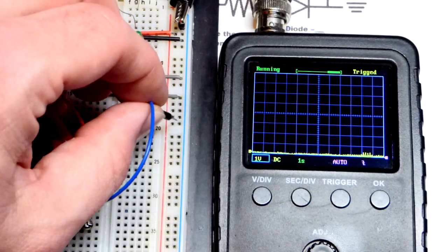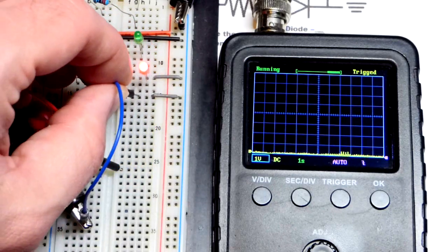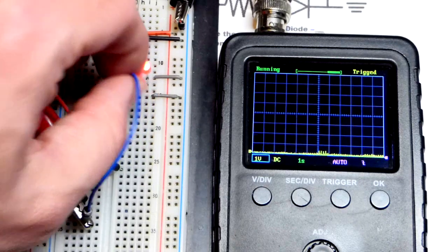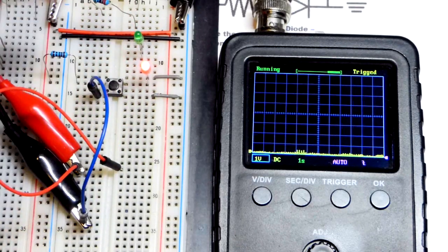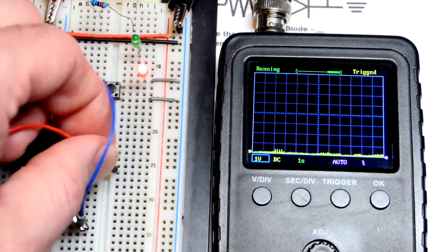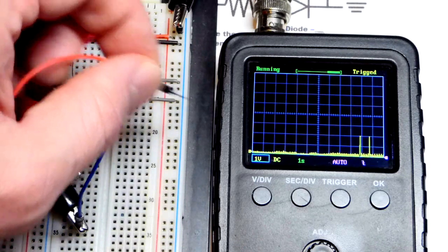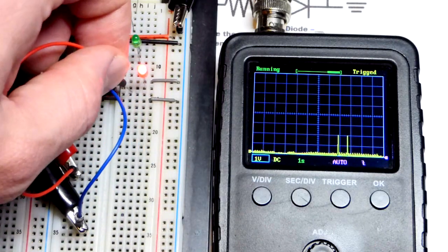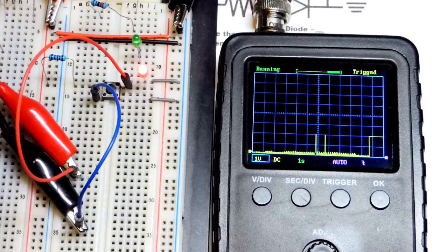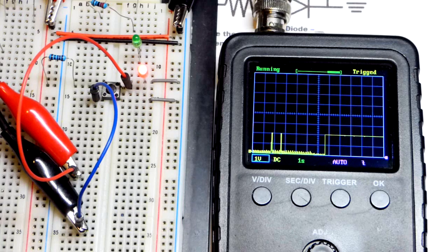So we're going to put this one to that spot. We could also put it to that spot. It's a direct connection, so it doesn't matter right there. We could even put it over here. It will work just fine. We'll look at that. I'll come up here and go to the long lead of the LED. You can already see I bumped it and we got some voltage. But there we go. That's 2 volts. That's the voltage that the LED is blocking while it is forward biased. It's forward voltage, 2 volts.